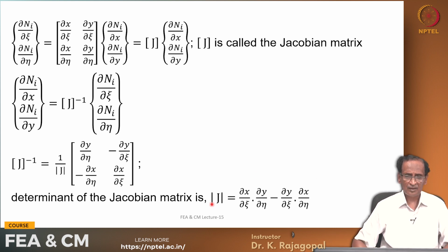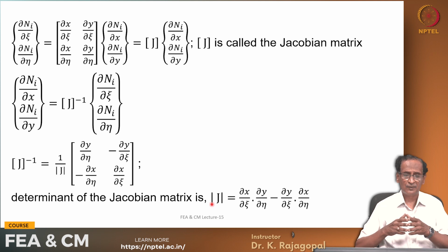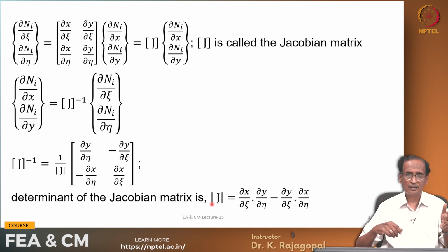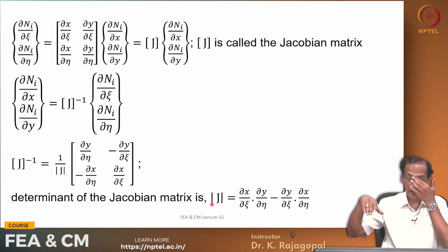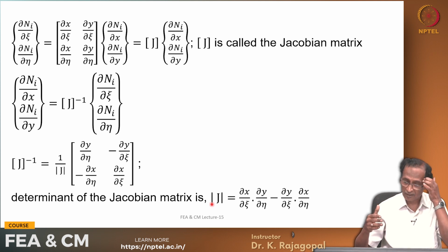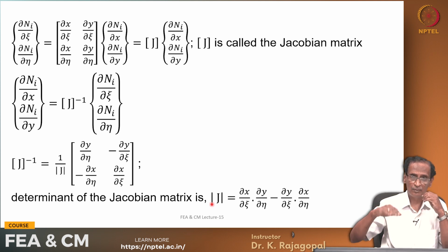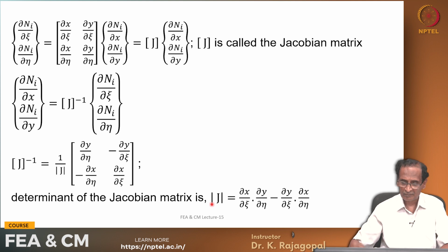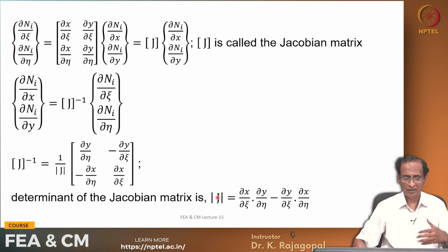The Jacobian should be positive definite for unique mapping, because previously we said some things, like all the internal angles should be less than 180 degrees, and the intermediate point should be within the middle third and so on, and the further check is done by this Jacobian matrix that we derive.